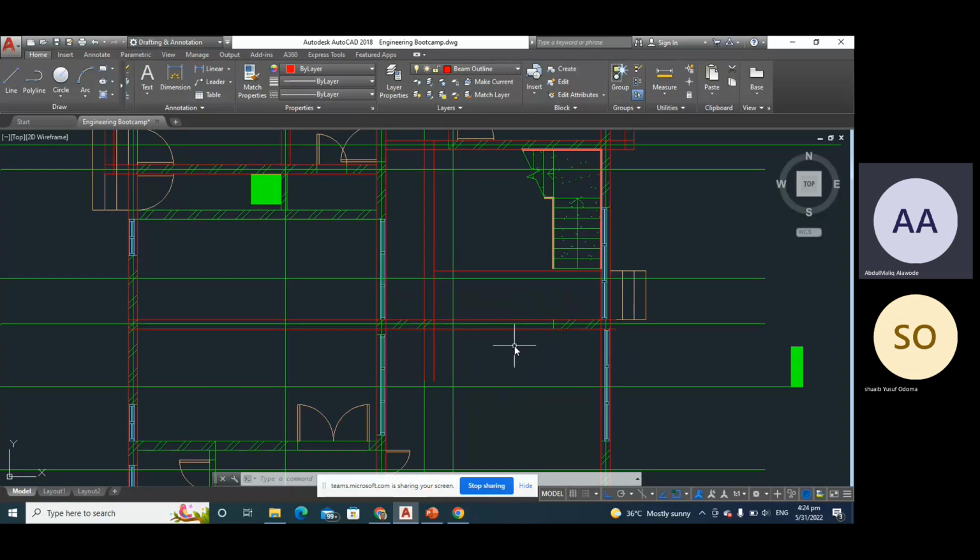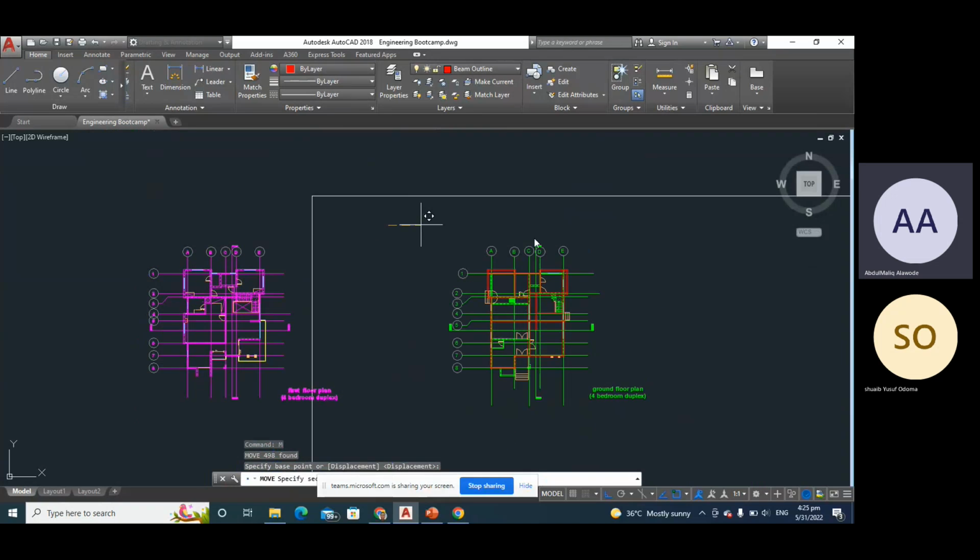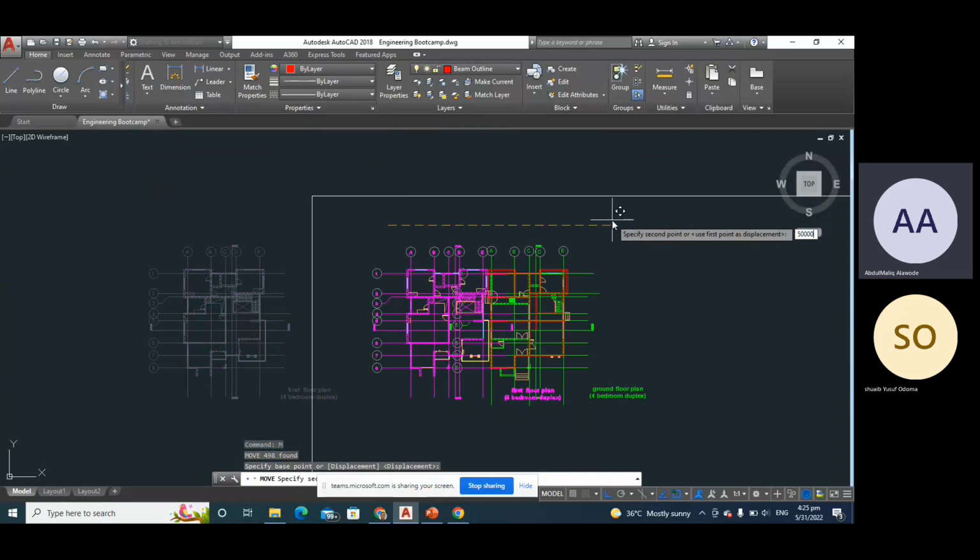Yes. Because if you remember our normal manual analysis of a cantilever slab, the moment is going to be at the top. So to resist the force, you are going to put top bars that will resist the moment for a cantilever, while for a simply supported slab, the moment is going to be at the bottom. So the reinforcement at the bottom is going to be the main one. Do you get my idea? Yeah. I believe when we get to structural detailing, we are going to talk at length on that because it's very important. So let's go back to what we are doing.